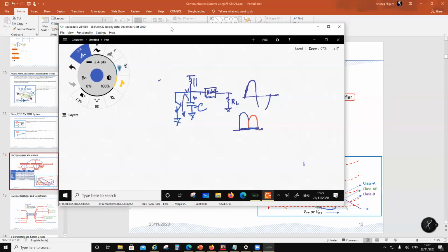So basically, parasitics, and let's say that there is a lead inductance also here. If there is a lead inductance and capacitance here, all the magnetic energy is stored in the lead inductance, and all the electric energy is stored in the shunt capacitor. Now, if I switch this on and off, the energy goes to ground, and I'm going to lose efficiency.